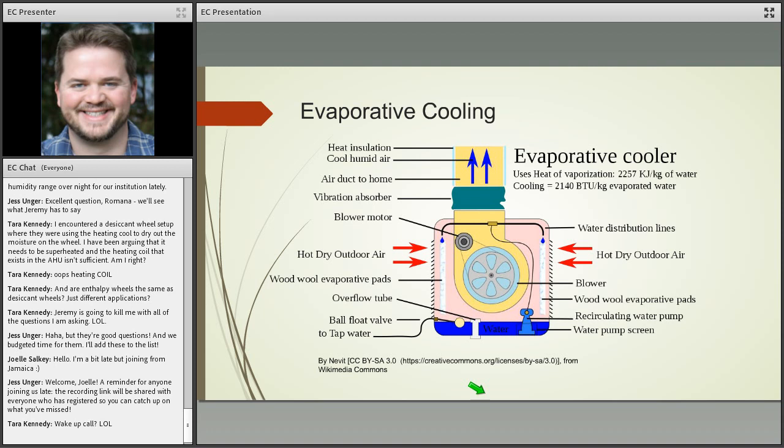Now, we don't see swamp coolers very often except in these very dry regions. And from a collections perspective, they're not my favorite equipment, primarily because that moisture aspect is very, very hard to control. And the amount of cooling that you actually get varies significantly by the outdoor temperature of the air. So if it's not a particularly hot day, you may not actually cool effectively because you can't evaporate enough moisture into the air. So these are systems that are really meant to create human comfort environments that can vary greatly across the board. When we try to put those into cultural heritage applications, my experience is that they don't work overly well. And most of the time we're better off using a different type of technology.